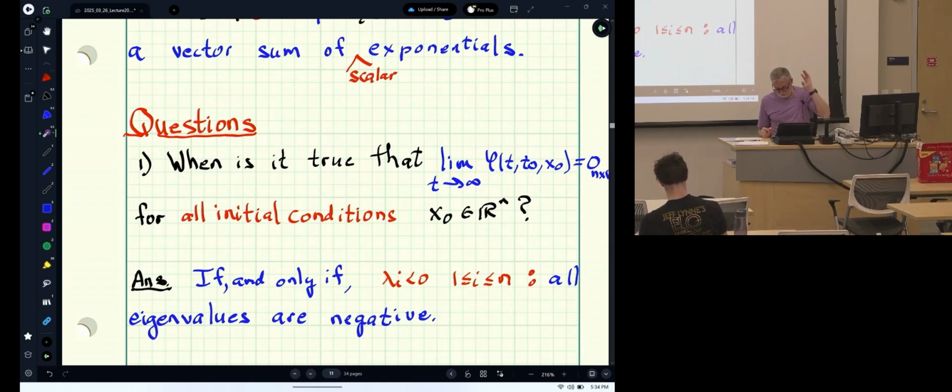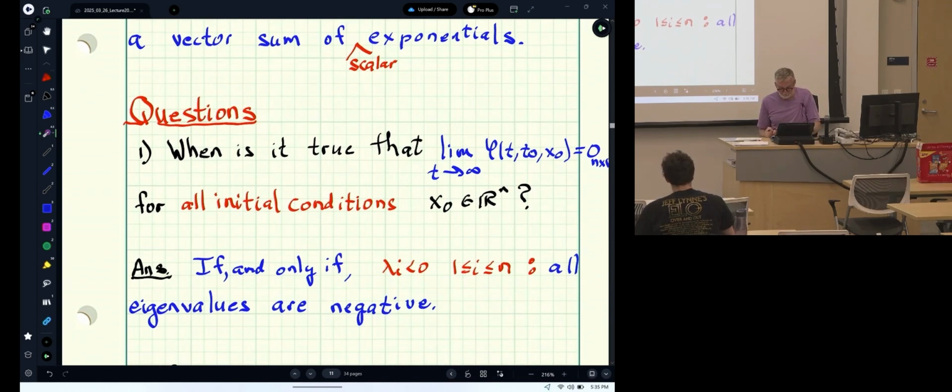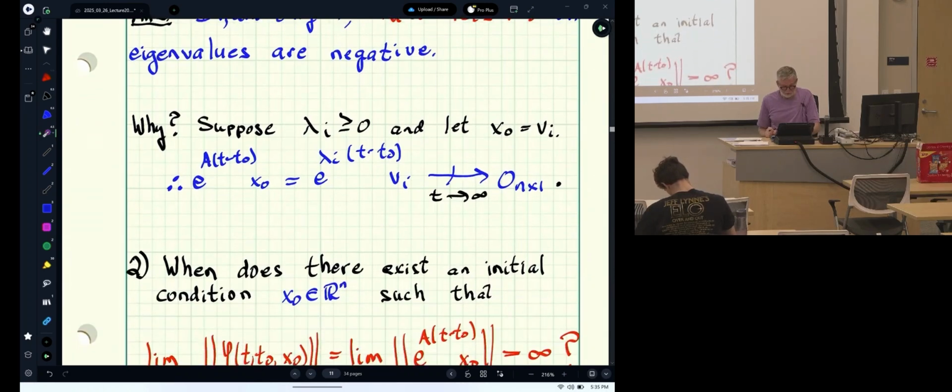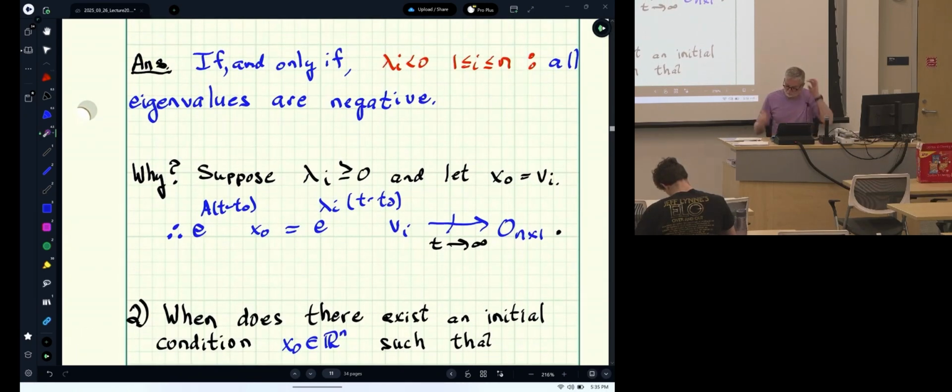So Justin, your Segway is stable. It's upright, it gets perturbed, it will return to the upright position if and only if, write down the model, look at the A matrix, x dot equals Ax, and calculate the eigenvalues, they need to be negative. And the why is, if you have any that's not negative, just take that initial condition. It's not going to zero.